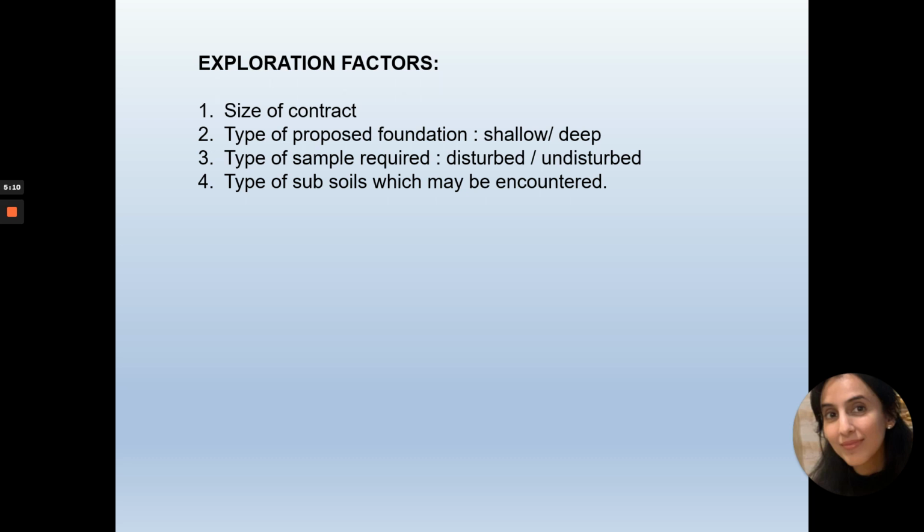Exploration factors. It depends, like I mentioned, on the size of the contract and the type of proposed foundation, whether it's shallow or deep. If you have a shallow foundation, you don't need to do in-depth exploration, because the deeper you go in the ground, the more expensive it will be.